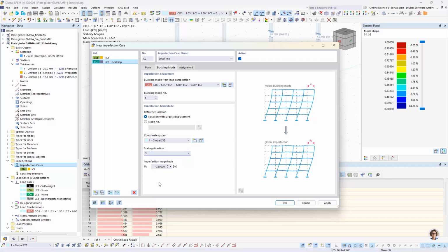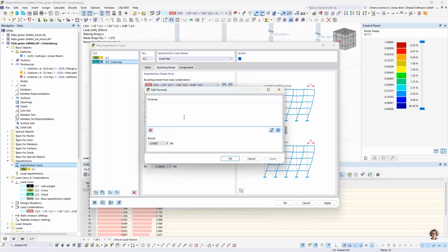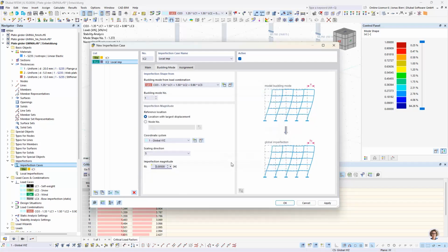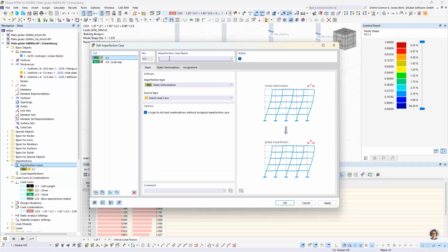And we also take an arbitrary deformation direction. We scale it spatially again, and as an imperfection magnitude, we set the minimum of the panel dimensions. So panel dimensions would be 4.5 by 1 meter divided by 200. It's always very convenient to just use the formulas to plug this in, and you don't need your calculator. You have a reminder if you are unsure, you can check the formula again and so on. So this is very handy. Okay, so that would be this definition.